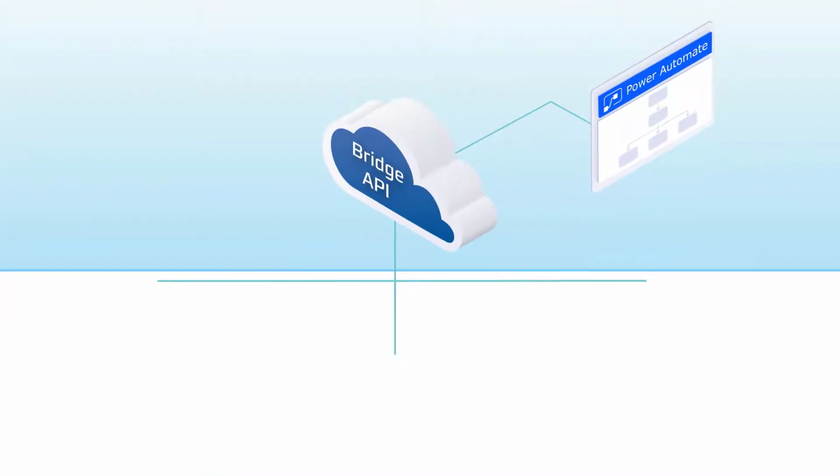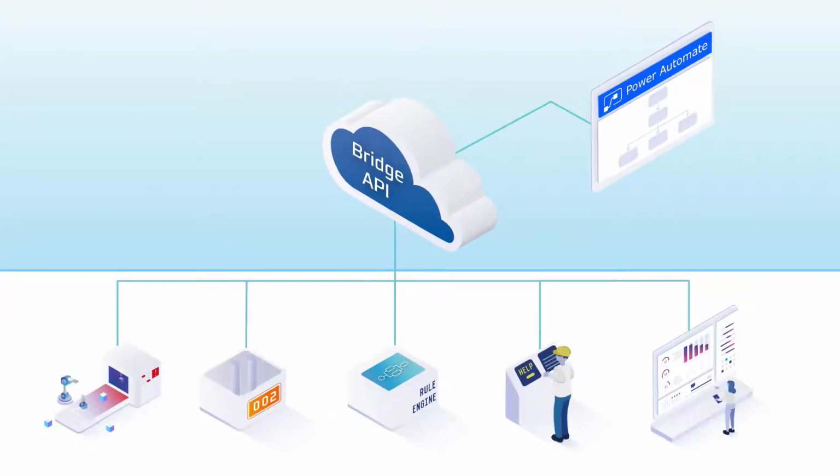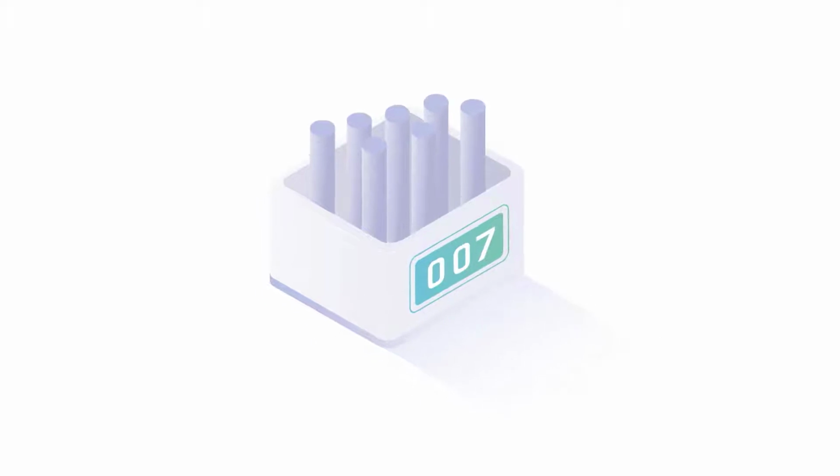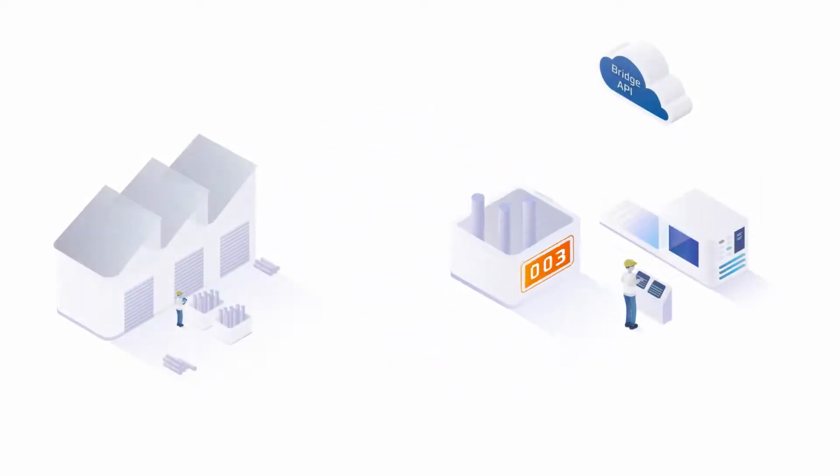Machines also track process data, like for example filling levels, pressure, or voltage. These could trigger a workflow as well. For example, you define a certain limit for a container's filling level of granulate. As soon as the limit is reached, an event is triggered causing a driverless replenishment system to get the suitable raw material from the storage facility before the container runs empty.